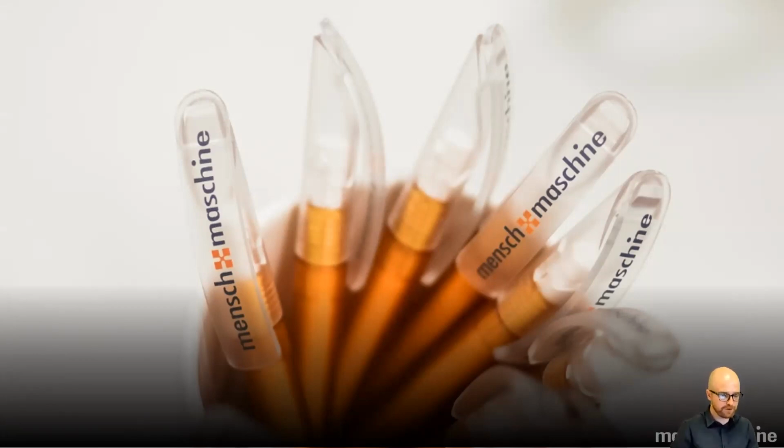So, a question from John. We can only see the linked models in the 2D sheets. So I assume the 2D sheets you'll be looking at will be the ones within the model or shared from the model. The reason for that, I believe it's being looked at, is because the links you are working with need to be cloud models, essentially. So they need to be ones that have been initiated through Revit into either BIM 360 or the new platform.